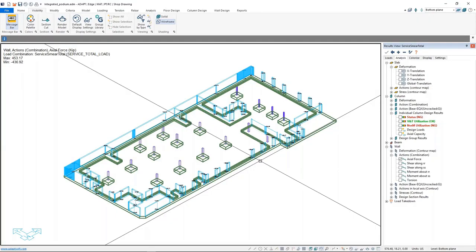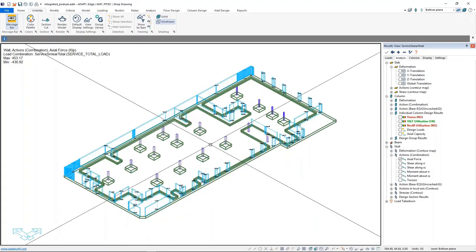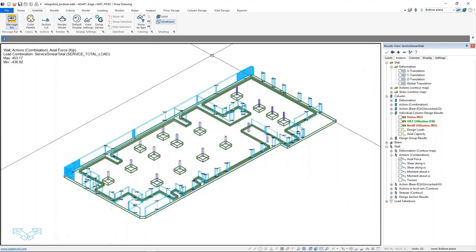I still maintain both load sets, and I find that in almost all cases the smear load is governing. This is just anecdotal evidence, based on this configuration. So I don't think there's any specific guideline. It's probably prudent to do both, but I see a lot of people get away with the smear loads as well. Let's move to the next question.